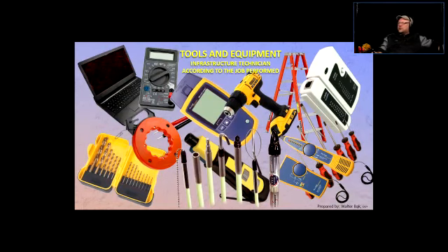And once you introduce that tone into the pair, you can go on the other side and look for that pair on the other side of the cable. And sometimes it's in a completely different room, if things are not labeled. So that's what we use for tracing the wires and checking them also for integrity, for structural integrity.